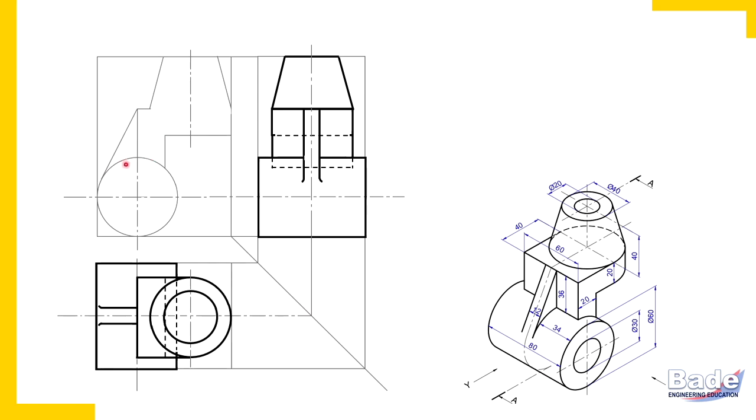Now vertical plate meets cylinder. So boundary between vertical plate that is this plate, that is this surface of the plate, and the surface, ring-like surface of cylinder. Boundary between these two surfaces, that is this edge, that is to be erased. So this is very important instruction I have given you. When two portions of an object get cut by a single cutting plane, then boundary between the two portions to be erased.